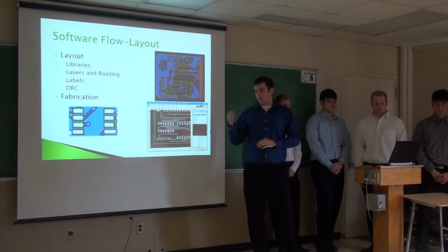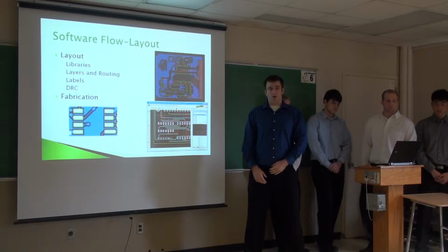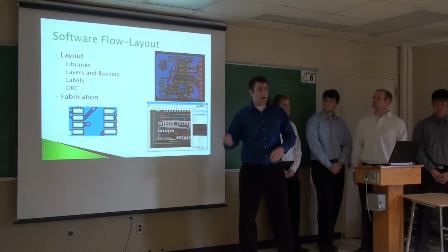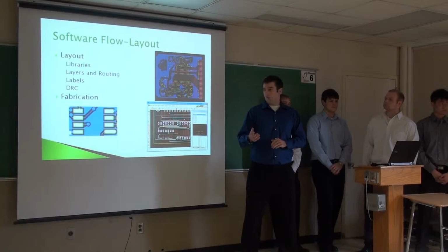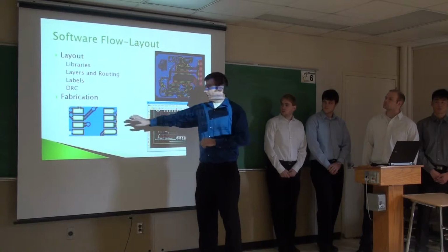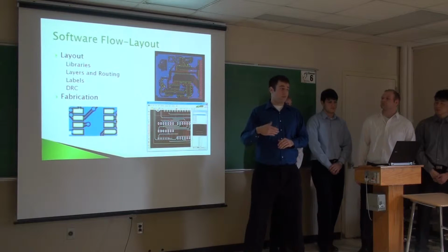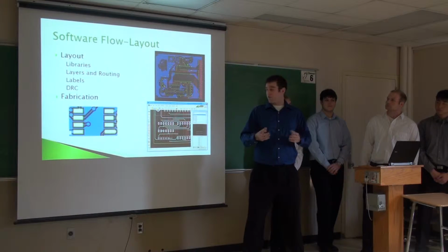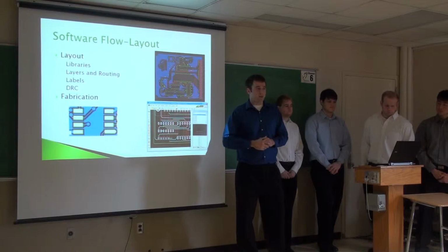And a quick thing, like I mentioned earlier, if you don't actually have your chip or component in your library, you actually have to make the layout as well. So to do this, if you have to custom make a layout for a chip, this is an example right here, and this is an 8-pad chip. And so you're going to actually have to go online, look at the data sheet, and they'll give you the dimensions for the pad, the spacing between the pads, vertically and horizontally, and you have to actually draw that.